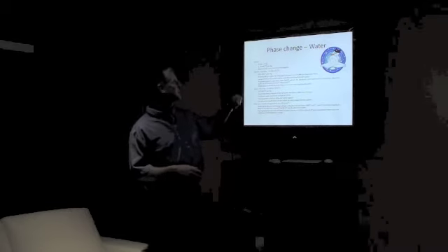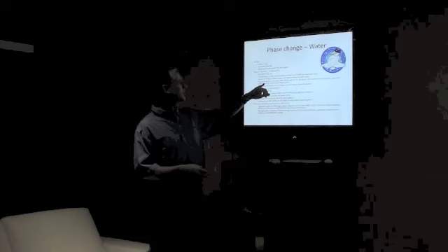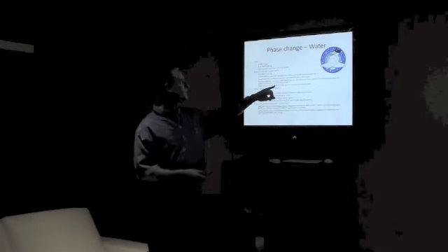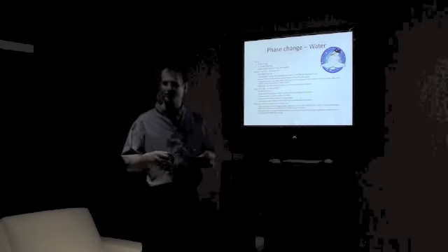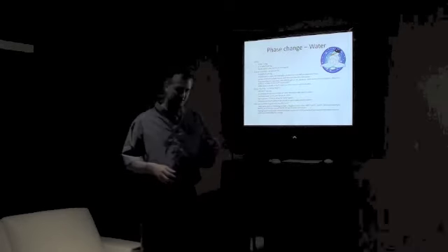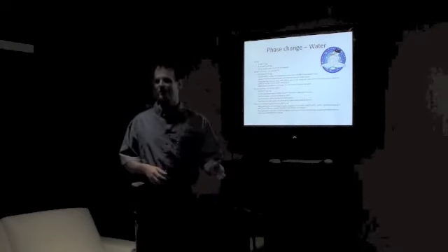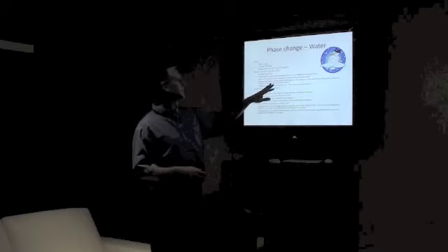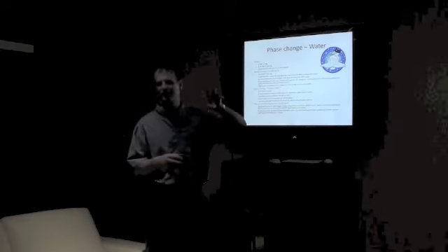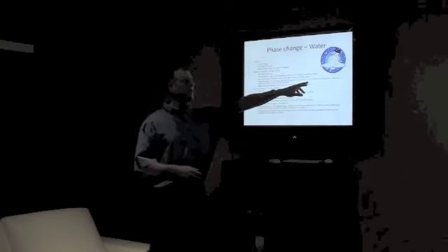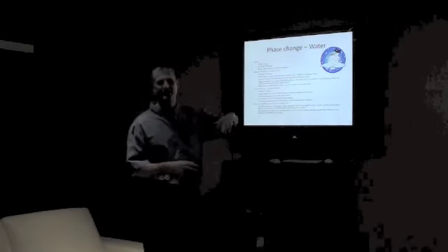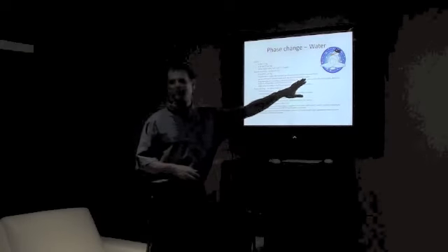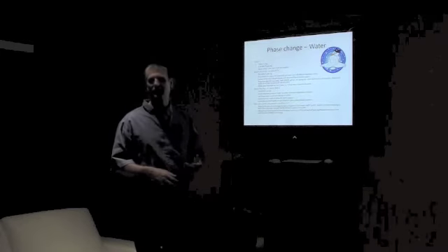To do that, we use an antifreeze solution, and in the solar world, we use a non-toxic propylene glycol as our antifreeze. For our systems here, we use 50% propylene glycol. Propylene glycol doesn't freeze the same way water does, where at 1 degree Celsius it's a liquid, and at -1 degree Celsius it's a very solid ice. This one sort of gels, and that starts around -35, and it becomes more solid. And at about -60, it starts to have these expansive forces. But in this whole range, -35 to -60, it's safe, but not really liquid.